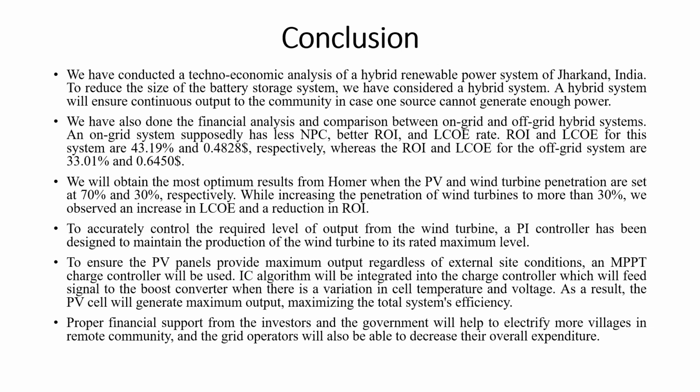To accurately control this penetration, a PI controller is developed and it accurately maintains the penetration percentage to get the maximum power output from the whole system. We also developed an MPP charge controller with an integration of the IC algorithm, because as we are getting more power from the PV cells, it is important to ensure that the PV cell provides the maximum power output all the time. And last of all, proper financial support from the investors and the government will help to electrify more villages in remote communities. Also, the most important thing is that the grid operators will be able to reduce their transmission and distribution costs.